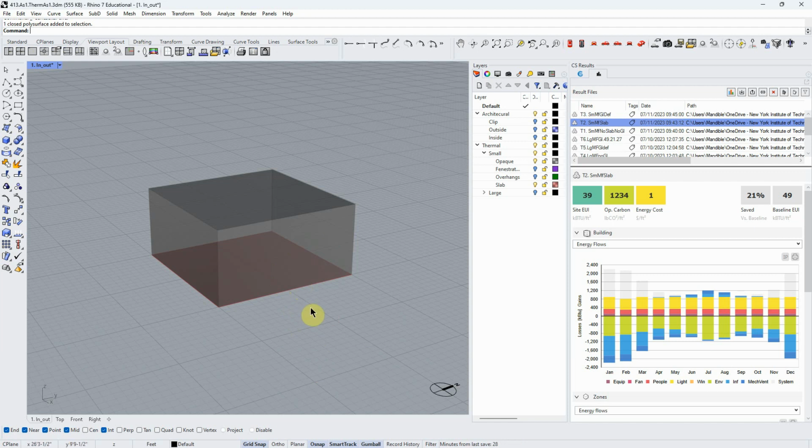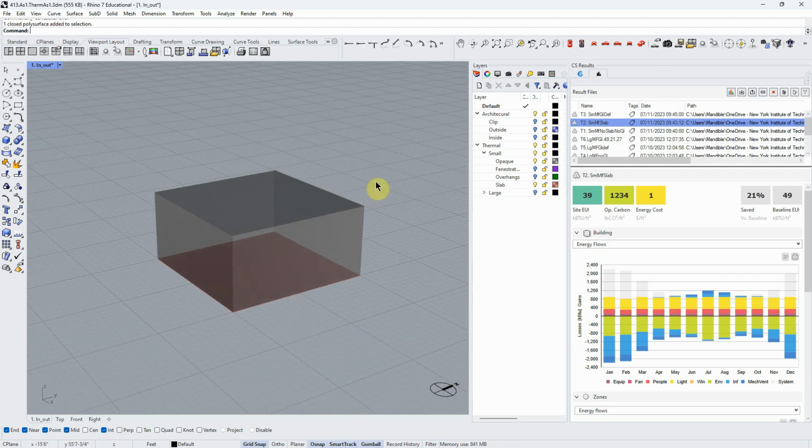Just say that if you imagine the ground is 50 or 55 degrees and the slab is touching it, and the air inside is heating up during the day, or we're having to keep it at a temperature higher than the outside air, it's going to be more efficient. It's going to have less heat moving through the slab, and so I think that's going to lower our heat load, which seems to be what's happening here.